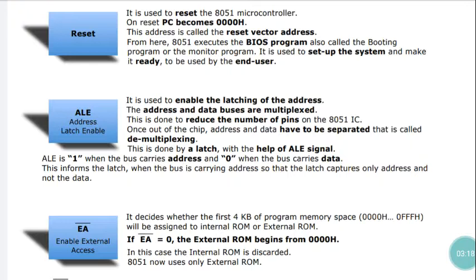The number of pins in the 8051 is 40. Among 40, 24 pins would be used only for generating address and data lines. If you make separate pins for separate signals, the size of the microcontroller may become larger. So, in order to reduce the number of pins, multiplexing is done. When you do multiplexing, the same pins are used for generating address and data lines.